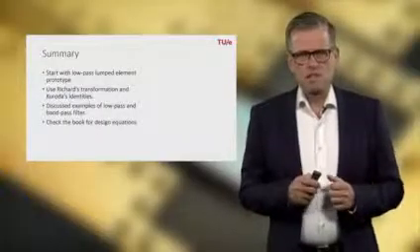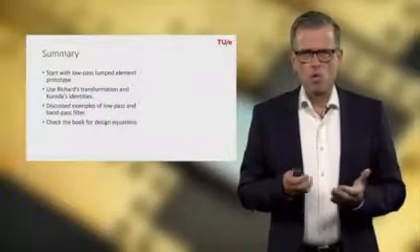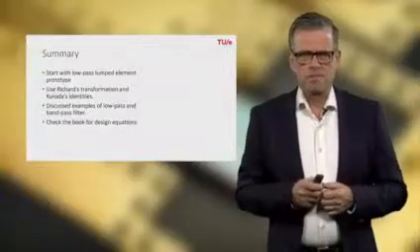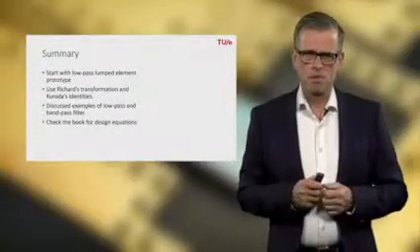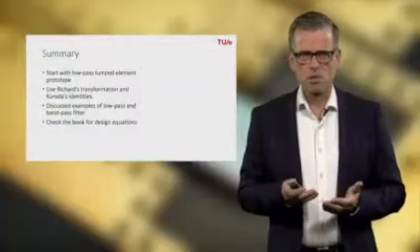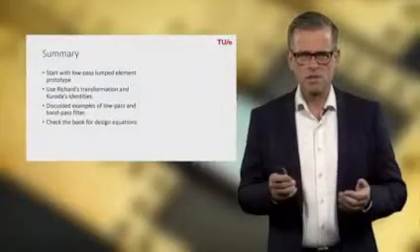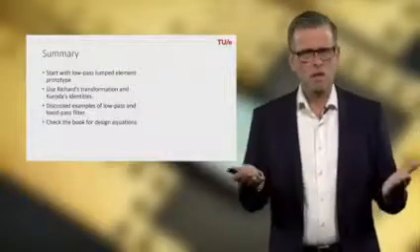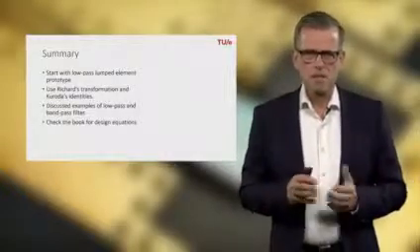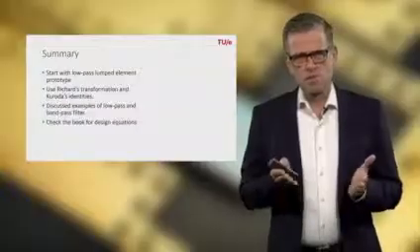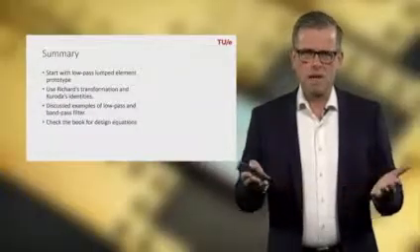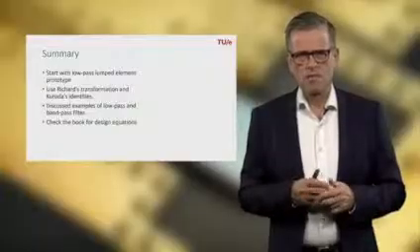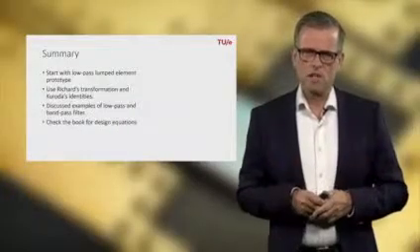So to summarize this web lecture, we always start with a low-pass lumped element prototype. Then we transform it using Richards transformation and Kuroda's identities to a transmission line version that we can implement in a certain technology, like a microstrip technology. In this web lecture, we looked into two specific examples, a low-pass filter and a bandpass filter, and checked the book for more detailed design equations.